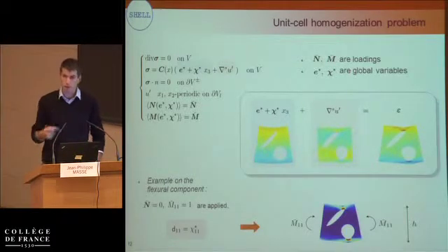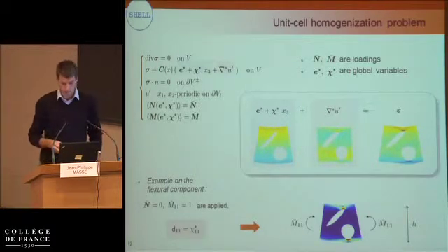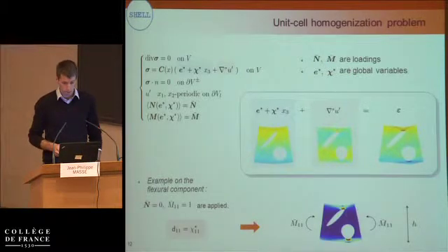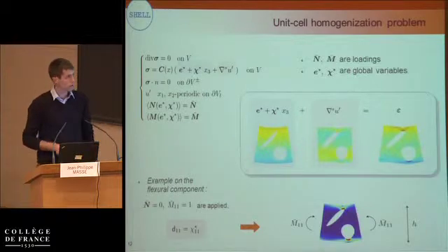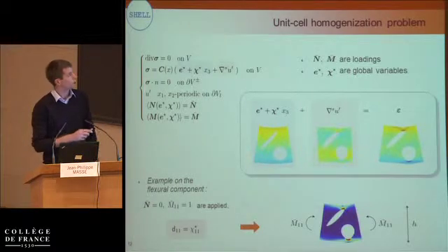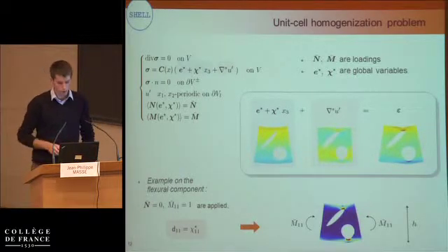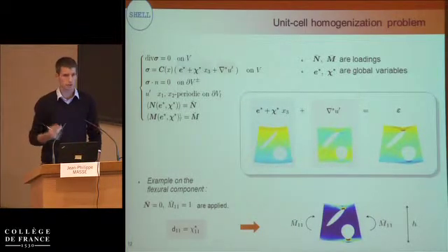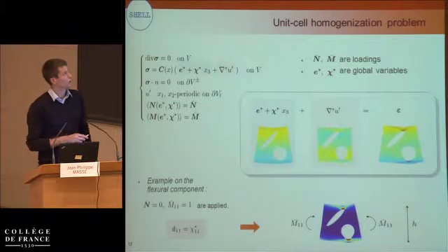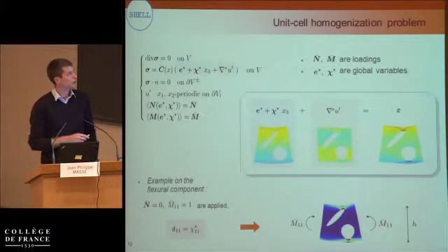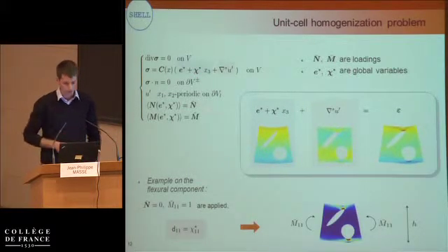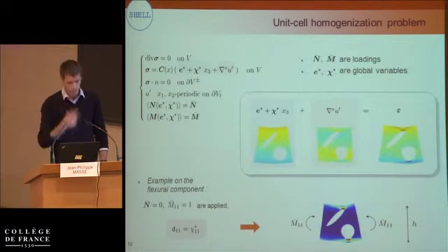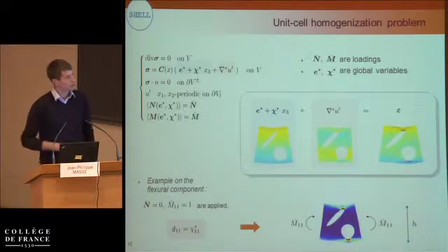So this is the problem we solve in order to identify the compliance components. This is the mechanical equilibrium, and what we do is, with a given unit cell geometry, we apply an average homogeneous tensile in-plane force and bending moment.